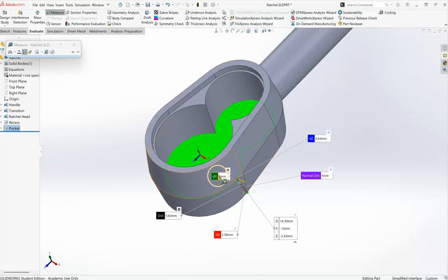We can see that the dy, or the delta y, and the normal are the same, and the normal distance is the straight distance between this face and that vertex, and the y-axis or the delta y is the same, and you can see that it's going in that same direction as our y-axis here. This is giving the dimensions from the origin, from where we clicked.